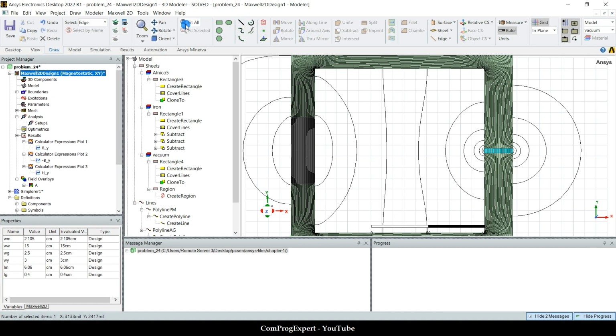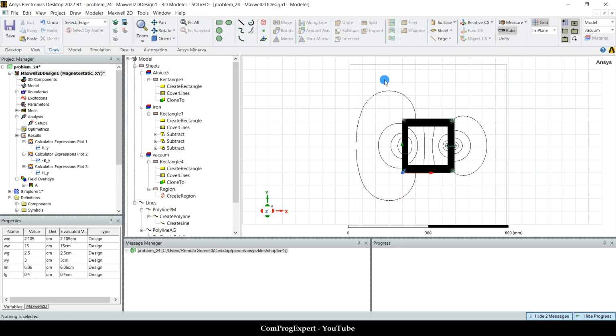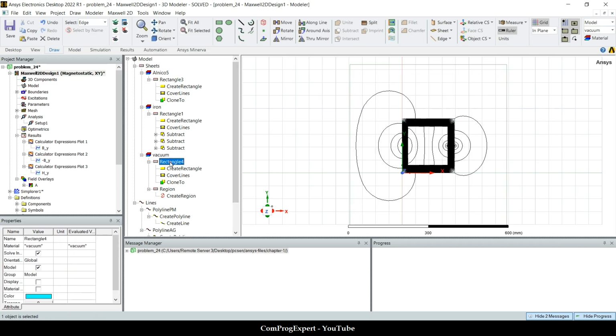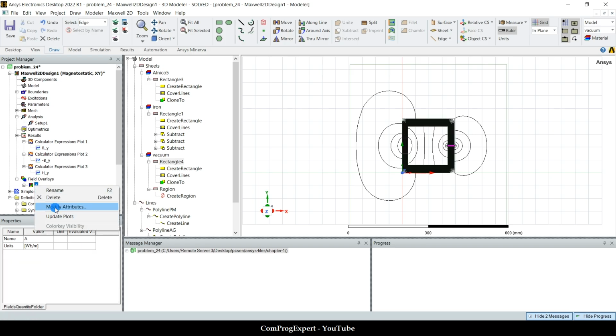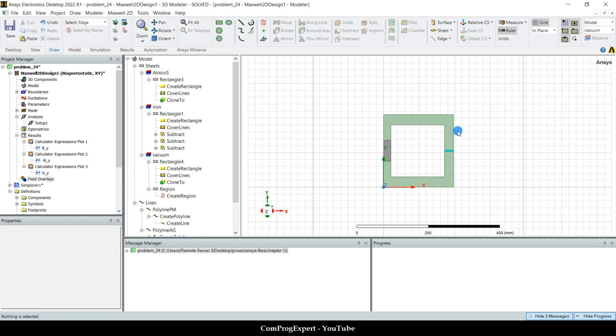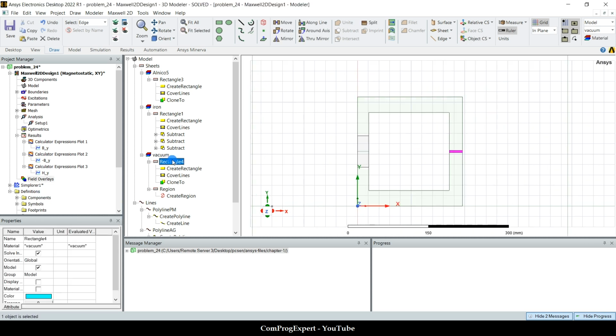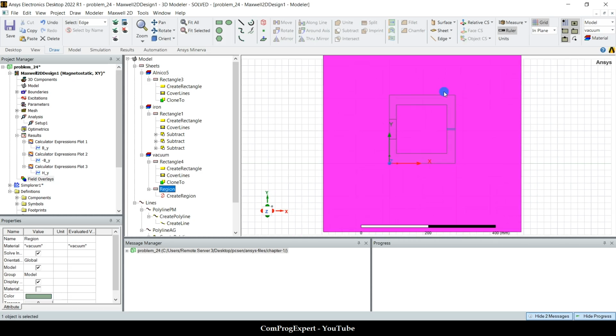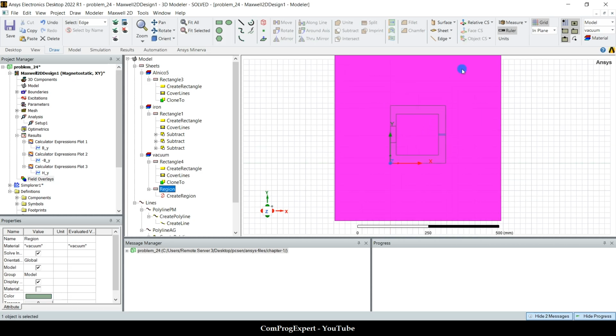Here in the ANSYS Maxwell model, we have this region, okay? And I defined, let me reduce the number of, or let me delete this. Again, we generate the plot. We have this air gap, we have this region. I am going to define a fictitious material.